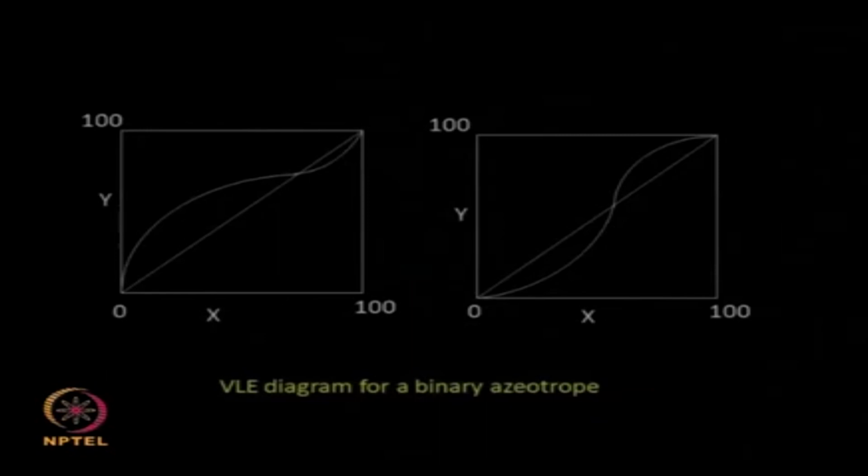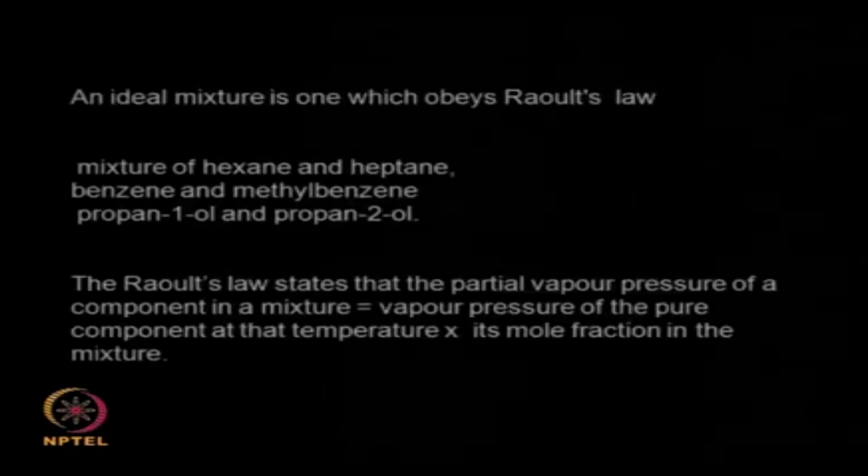So there are different types of distillation columns we can use, and they are called tray columns, plate columns, packed columns. So we can have packed material inside the distillation column, we can have plate type of material, or we can even have tray type. So all these help in mixing the vapor and the liquid together, bringing them in close contact with each other, thereby you can get a better separation. So these are the main advantages there.